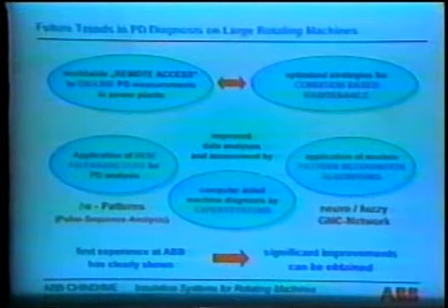PD diagnosis is not a tool that allows discovering all insulation problems within stator winding insulations, e.g. pulseless discharge phenomena, or all phenomena associated with low voltage but high currents can in principle not be detected by PD measurements. So PD diagnosis needs to be combined with other diagnostic tools like visual inspection or other dielectric tests, and it needs to be integrated into a general diagnostic concept.